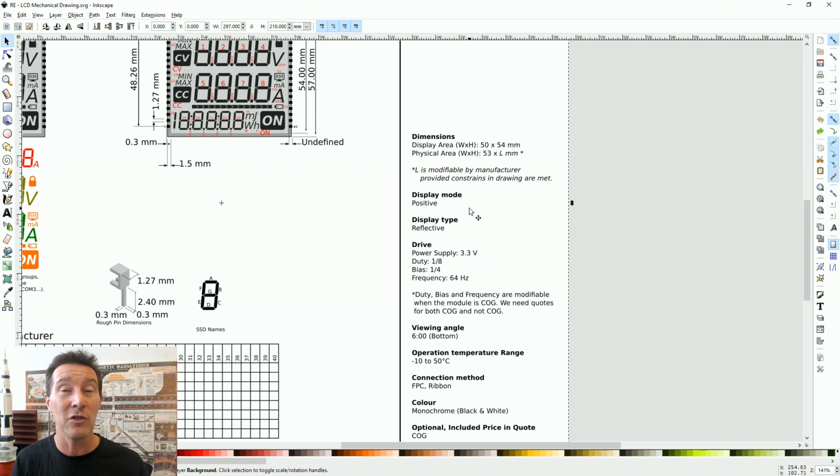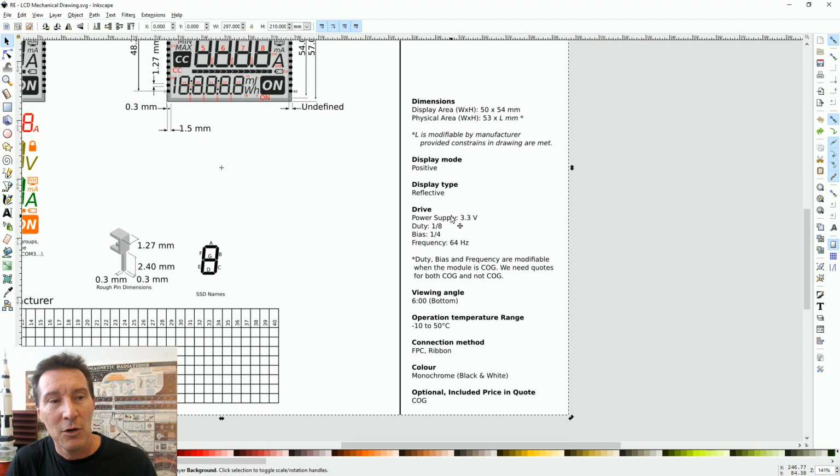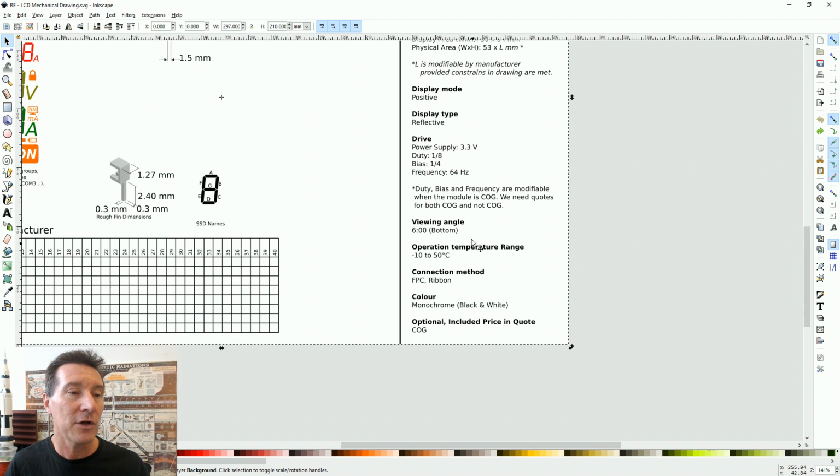It might be harder for them. So just be aware of that. Give them as much flexibility as you can, but we're saying a nominal power supply of 3.3. We're saying the duty cycle, the 1/8, the bias of 1/4, which I've covered in a previous video, and the frequency 54 Hertz. And the viewing angle, now this is an interesting thing.